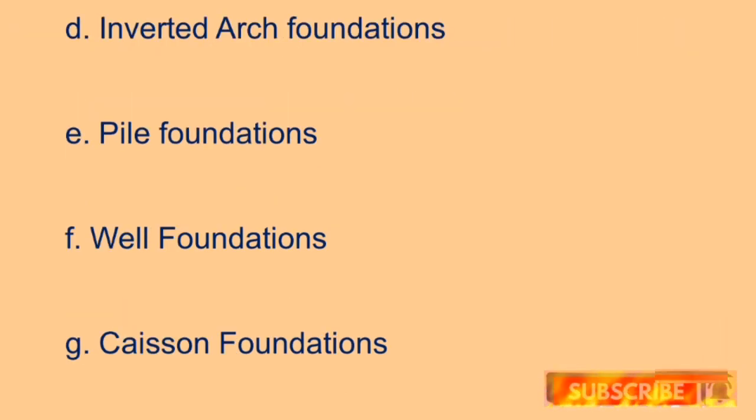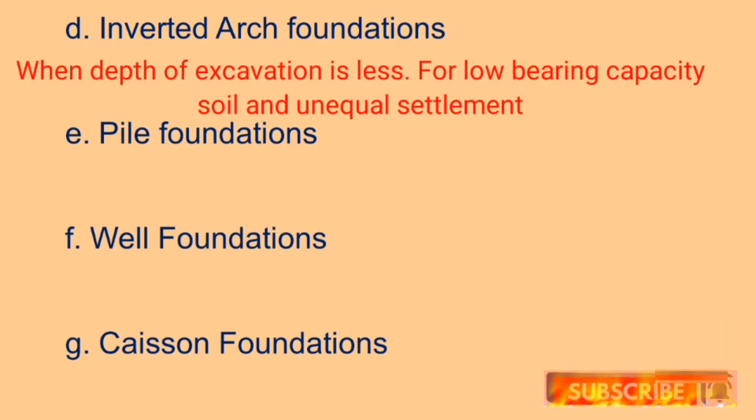Fourth one, inverted arch foundations. Inverted arch foundations are suitable when the depth of excavation for foundation is less. It is best suited where the bearing capacity of soil is less, especially when the subsoil has soft pockets and there is possibility of unequal settlement.